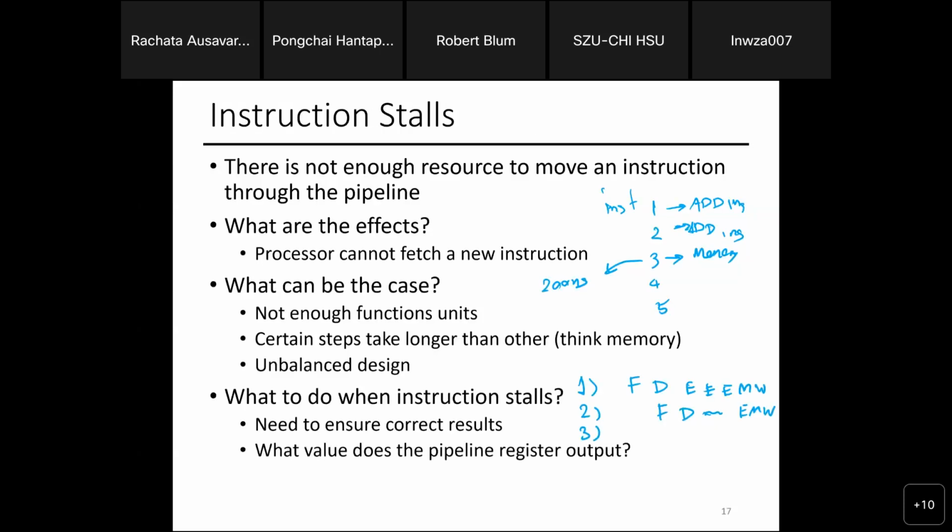These 2 bullet points sound obvious from your point of view, and they are obvious. The reason I put them there is that if you design a chip for the first time, this is where most of the hardware bugs in your design will come out, because you accidentally put the wrong output. I did it many times before, when I was doing the lab.